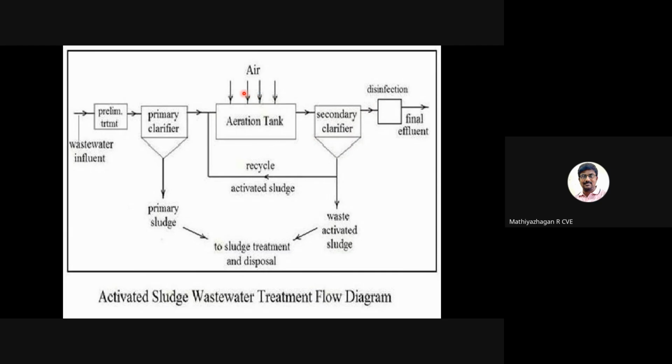So that is, we are introducing air as well as the activated sludge. We are maintaining the MLSS and MLVSS, that is, mixed liquor suspended solids or mixed liquor volatile suspended solids, and the F/M ratio, food to microorganism ratio, also called organic loading rate. Because of that, we are returning some activated sludge again into the aeration tank to maintain the F/M ratio as well as the MLSS concentration.